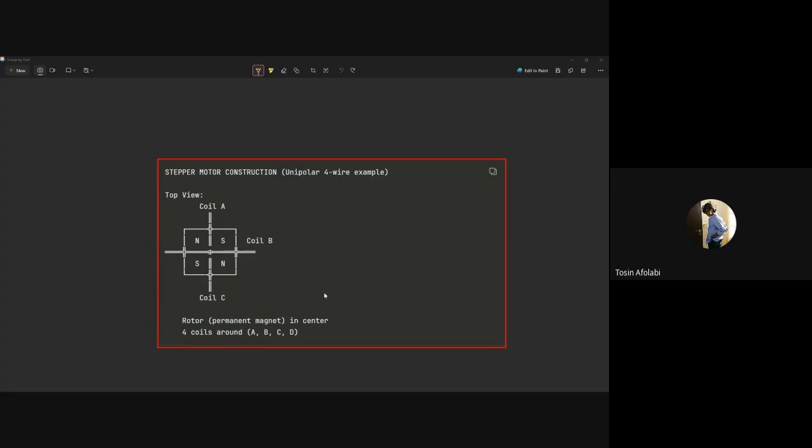We have half step, that is 8 steps per cycle. So that's 0.9 degrees per step. That's smoother because the small steps are covering a smaller angle of the revolution. It's smoother, but also double the precision because you're cutting down the window from 1.8 to 0.9 degrees per step.